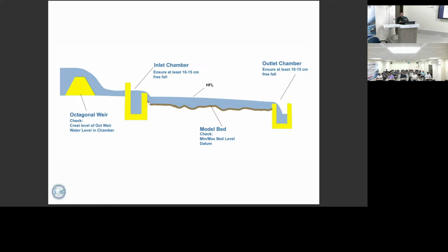So in our model, one pump has a capacity of 20 cusecs, and we have two pumps. But after every loss, because it is an old system and the canal will also have a lot of seepage, and pump capacity may also be lower, when you get the ultimate discharge you may not get 20 cusecs from a single pump. You may get 10 or 7 cusecs. So keep that 7 cusecs in mind and design the scale. Then it comes to space, which is okay. You will not have a problem with space; even in Nihari you have got a lot of space. Space is not a constraint.